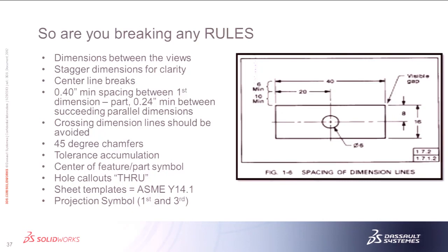Centerline breaks. This is the big one. Whenever you have holes, there should always be a little plus sign. You should always see a little plus sign and then a break into the next one. So that's pretty big. And then on the corners of the part where it says the visible gap, you should always have that spacing.